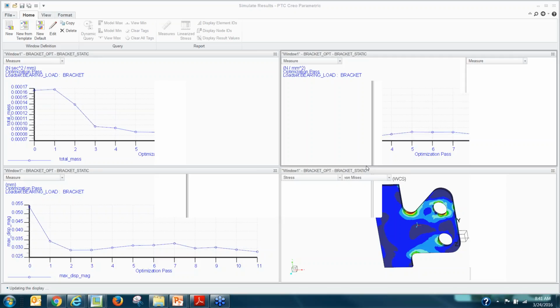When I say direction-based, you can apply non-isotropic materials, wherein in your material definition you can assign the properties based on direction. However, you might run into situations, like in the example you're talking about, or composites where you have multi-layered materials with different directions, ply thickness, etc. The way you simulate that in Creo Simulate is using advanced shells.